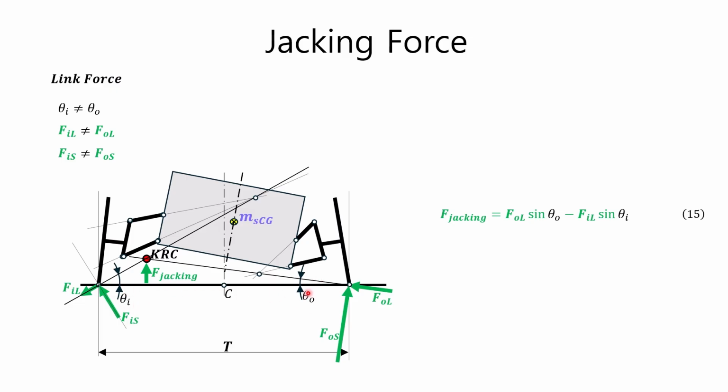The jacking force is a force that supports the sprung weight in the vertical direction separately from the spring force. When cornering where large lateral acceleration occurs, the jacking force plays a role in supporting the sprung mass so that the lower part of the vehicle does not contact the road surface. This is very helpful in preventing the lower part of the vehicle from contacting the road surface when large lateral acceleration occurs in a vehicle designed with a low ground clearance to reduce aerodynamic resistance.